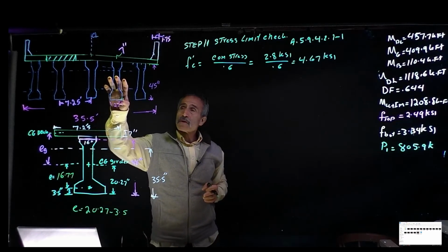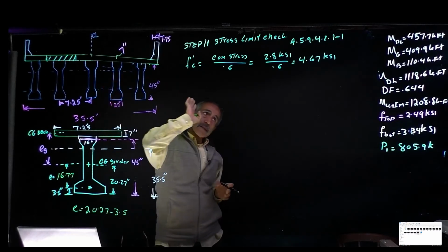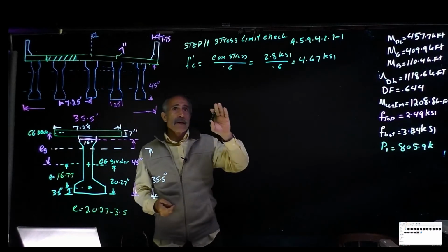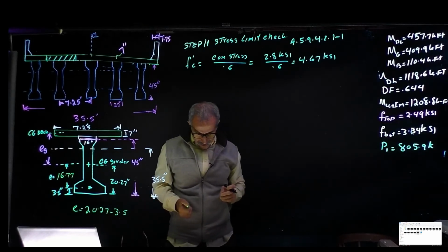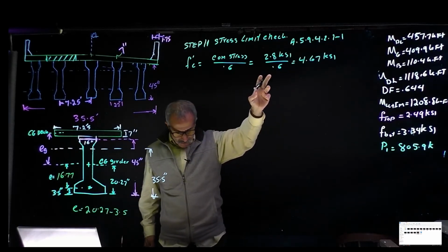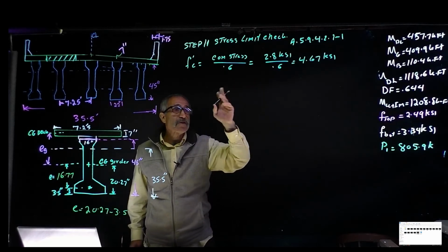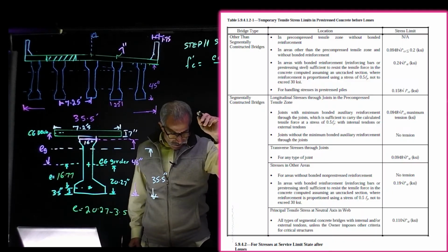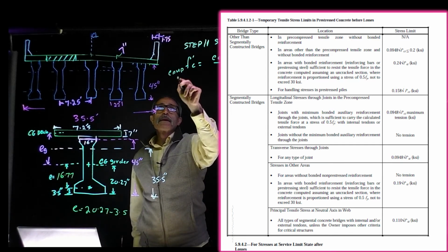It's pretty close. Normally we do about 7,000, 8,000. So let's just go with the problem for now. The compression stress passed. Let's find out if we can find the tension one. So for AASHTO, same thing right there, and then in AASHTO we can find the tensile stress for a pretensioned member, and that's going to be tension. This was compression. Now tension.